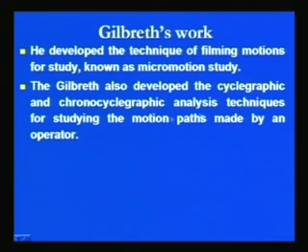Gilbreth also developed the cycle graph and chronocycle graphs for analyzing the motion paths made by the operator during the work. In the cycle graph, for studying the motion of the body parts such as hand or the head, a light source is fitted, and using stereoscopic cameras the movement is recorded to see the path of the motion of the worker or the body parts during the operation.